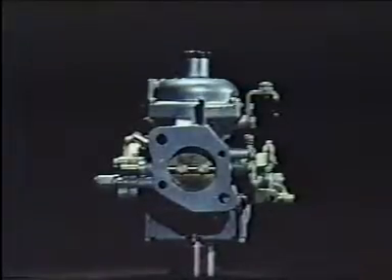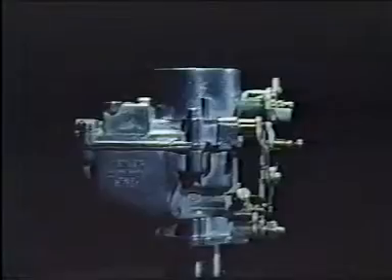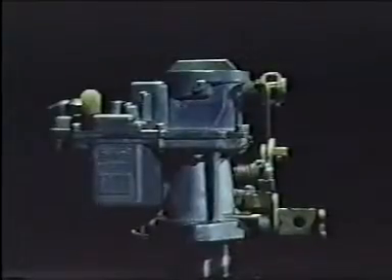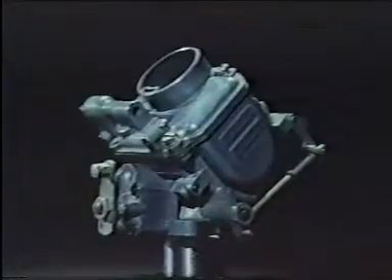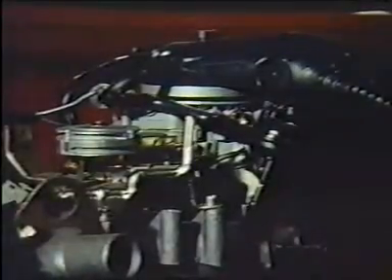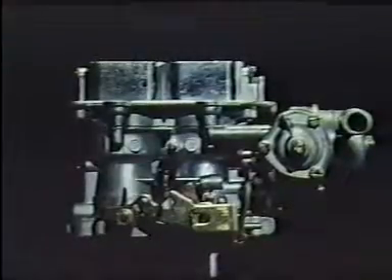The carburetors we have described are only two of many kinds. Although the principles are the same, individual engine requirements have produced many modifications of design and manufacture. In higher performance motor cars, maximum power is obtained by drawing in as much mixture into the cylinders as possible. A single carburetor is not always sufficient for this purpose. And one development which meets the need is the twin choke carburetor.